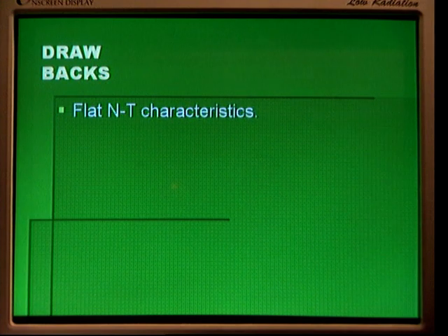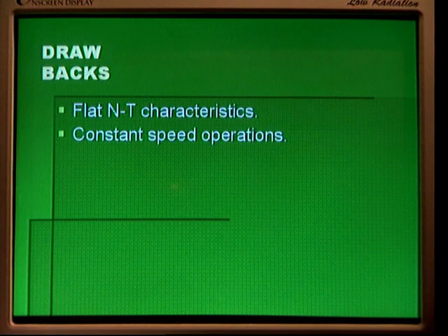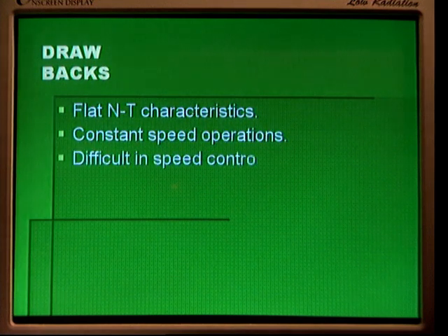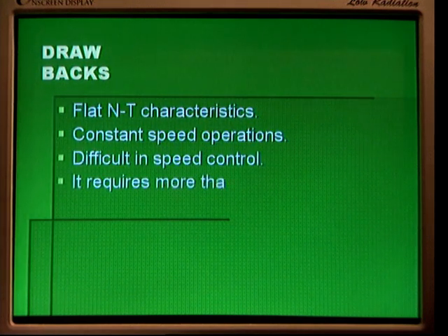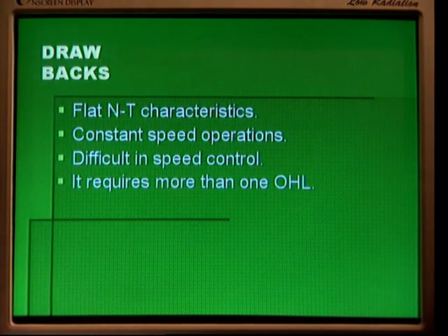Even then it has some drawbacks: flat speed-torque characteristics, constant speed operation, difficulty in speed control, and it requires more than one overhead line in the case of 3-phase. So these are not suitable for traction purposes.